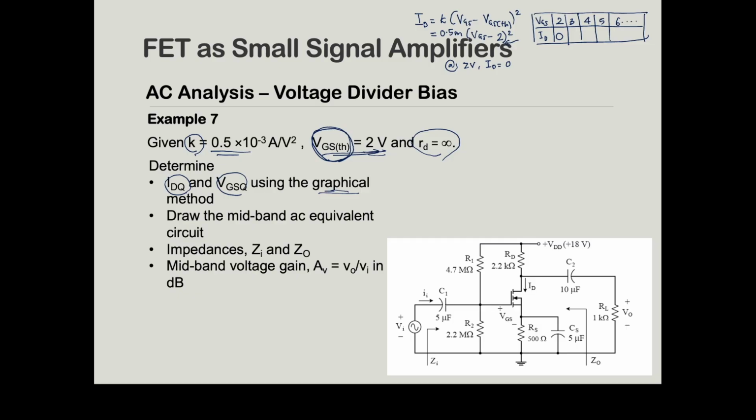Our suggestion is that you usually draw up until the value of VDD. But if the value of VDD is too large, like 40 or 20, drawing up until 10 or 15 is also okay. And you can choose your increment properly. Perhaps you can increase by 2 or 3, you don't have to do it one by one. The smaller the increment, the more detailed your transfer curve will be.